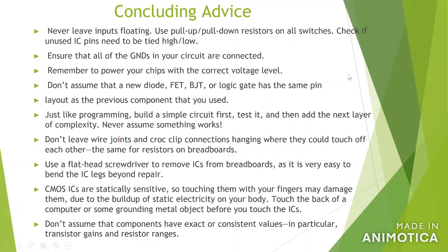All right, so in this chapter, we introduced many electrical components. Here is some concluding advice. Never leave inputs floating, so you want to use pull-up and pull-down resistors. Ensure that all of the grounds in your circuit are connected to make sure that you don't burn your circuit. And remember to power your chips with the correct voltage level.